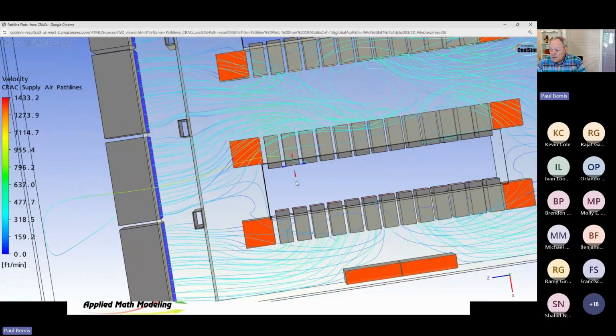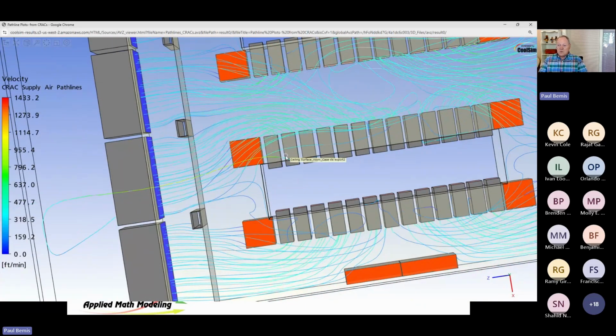In this model, what I've done is I've modeled each rack really as 19 inches wide, because 19 inches is the width of the server. Then you have the rack rails leaking, and then you have the containment leaking. They both leak. The amount of leakage is proportional to how well it was installed, but you have to assume some kind of leakage because they do. I think I have this one probably set at about 10% because that's not an unusual number. 10% leakage. It's hard to know without laboratory testing.